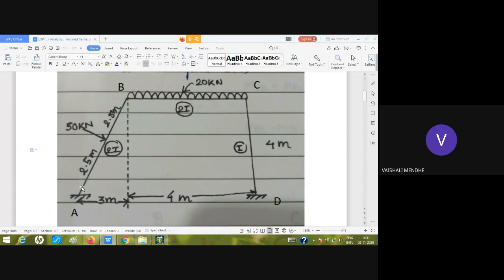Okay, now before creating this model in the software, the very first thing we are doing is finding out the coordinates of all the four nodes. Every time we are doing the same process because we are going to use the coordinate method. Every time we enter the values of coordinates, we get the nodes, and then we draw the frame. So before proceeding in the software, first of all, we'll have to note down the coordinates of A, B, C, and D.